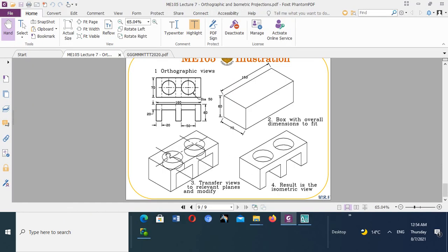There is a second circle, but you find out that now this circle is forming this top circle. But when you are viewing these things in isometric view, you should see that part to show that it's a through hole. So we must draw again these two holes, which are offset from that top layer of holes. Offset how much? 20 down to show that it's through hole.